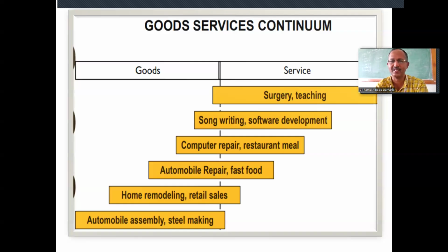They check the air filter and engine oil filter, replace the engine oil, clean the air filter, clean the engine wherever required, check all the play in the clutch, check the gearbox, any noise, any loose bolts and nuts, whether all the systems are working properly or not: electronic, electrical, mechanical, and hydraulic systems in brakes and power steering, all the motors, all the lights.